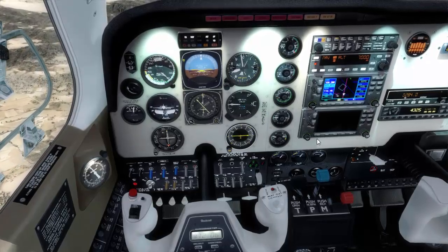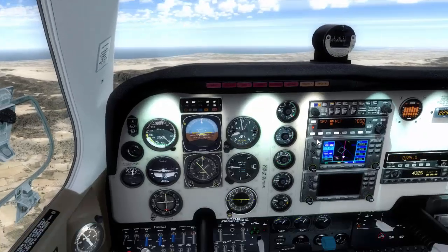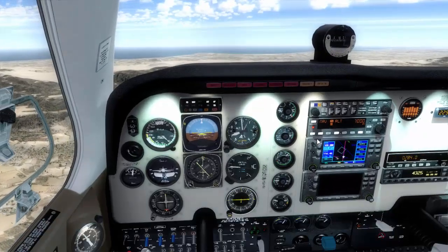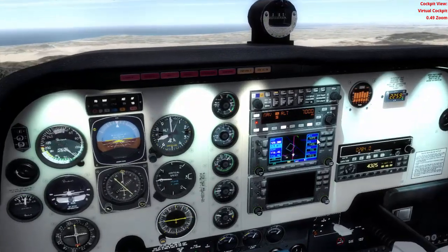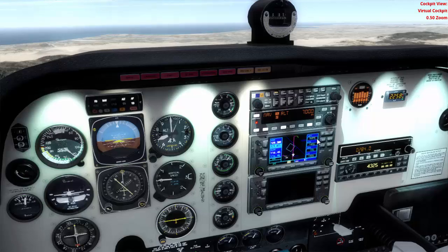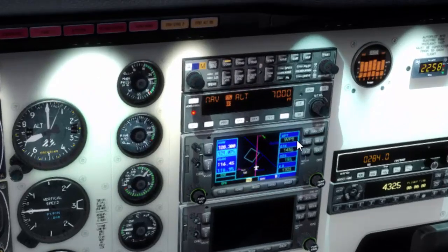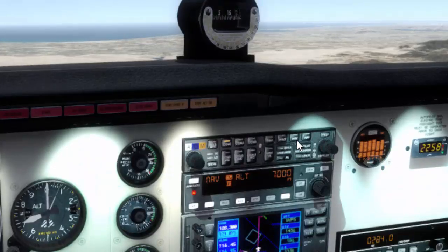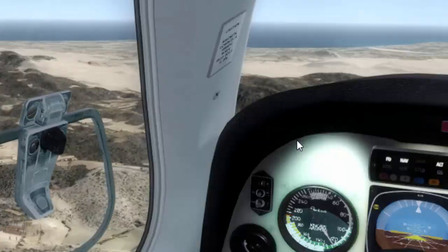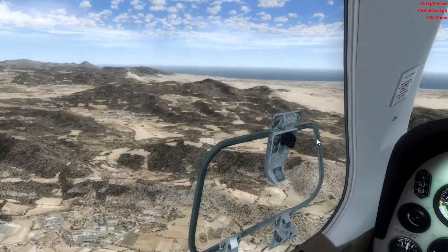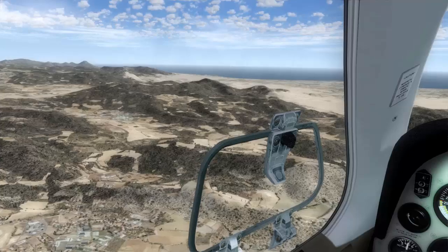So we are applying right now a bit more of blue lever, more RPM, because we don't want to limit the speed of our engine, and we are applying a bit more of black lever to give a bit more power to the engine, okay? And we are very close to Ibiza, okay? And the manifold pressure instrument again is showing us the value. I don't see very clear information, perhaps 23 or 24 inches of mercury.